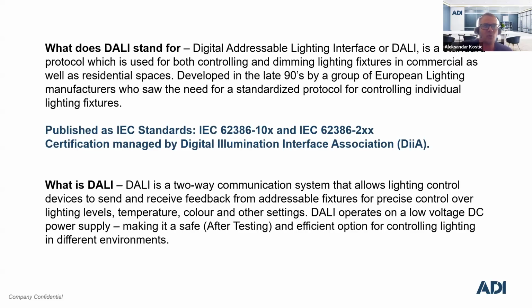projects, while DMX is more oriented to commercial, where we have full color spectrum transitions, and DMX does those full RGB color spectrum transitions best, as it is the fastest. On the other hand, in residential projects, we typically have changing of the temperature of the white, which DALI handles really well. So what we are seeing most frequently within residential projects are fully tunable white LED fixtures controlled by the DALI protocol.